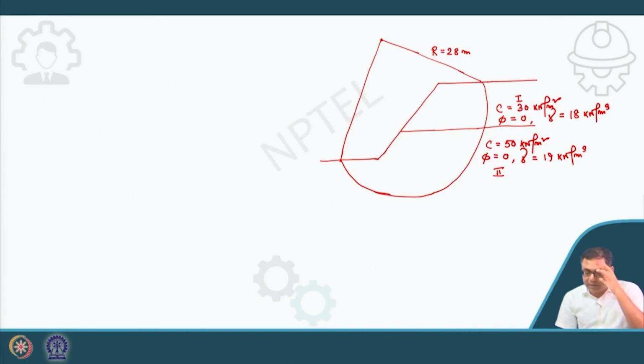Okay, and for this slope, its area has been determined. The centroid of each failure mass has been determined. That means you can take small segments, add those areas, and calculate the centroid based on those small segments with respect to O. O is your center, and this is the centroid, that is A.